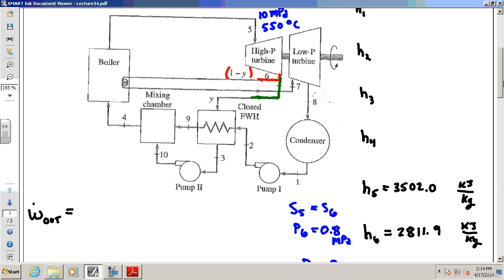That's super close. It's mass flow rate times H5 minus H6, because H5 is greater than H6, and otherwise you'd get a negative number. Now, is that wrong to get a negative number? Not really, but remember when you write the first law, you would write it H6 minus H5 like you said. But you'd have a negative in there: negative work equals negative. I'm just going to keep things positive, I think it's going to be easier. So I'm going to write m dot times H5 minus H6, and I'm going to try to keep everything positive. Okay, now that's not everything.